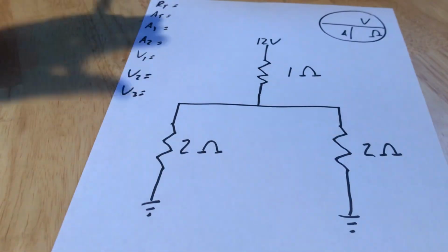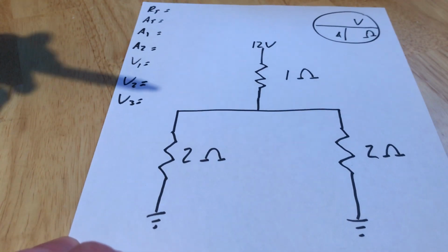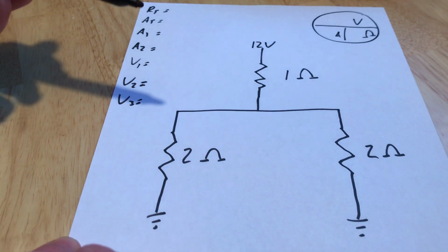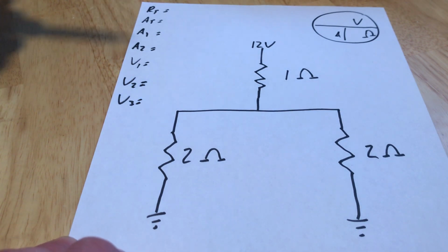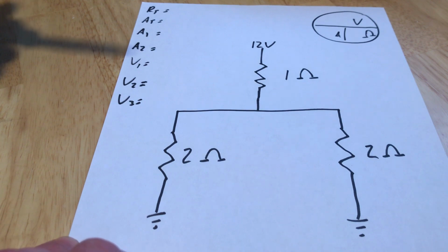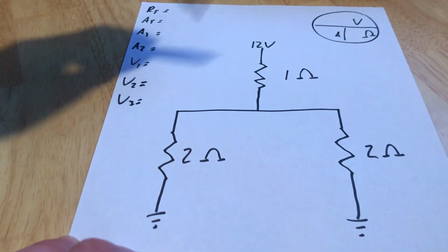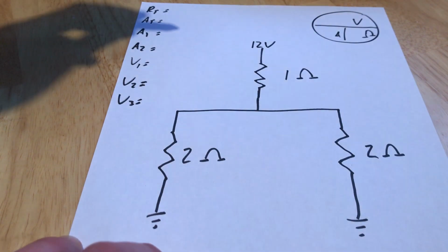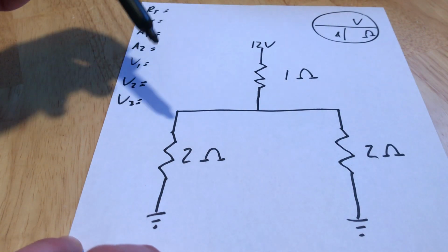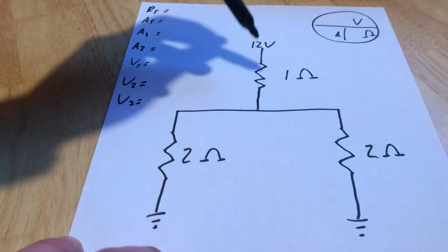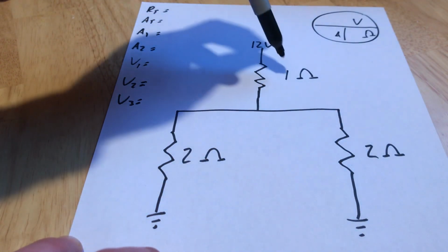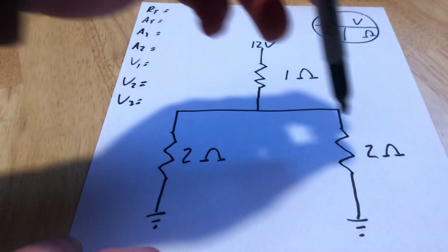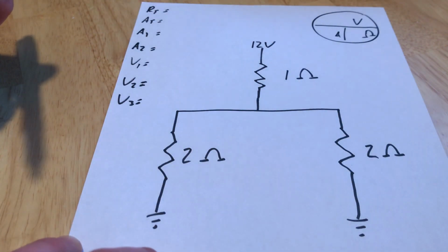Doing great. Masters of our own reality. But now, here comes, dun dun dun, the series parallel circuit. What on earth are we possibly going to do to solve this one? So, this one here, if I'm going to go for total circuit resistance like I always seem to, what I need to do first is figure out what my parallel circuit's resistance is. The series part of this circuit, well, that's easy. It's got 1 ohm of series resistance, but how much resistance is there here?